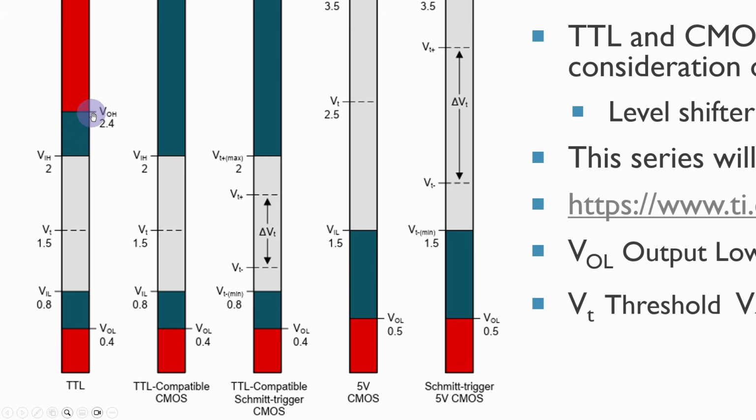Now this is actually underneath the guaranteed minimum output voltage of 2.4 volts, but it was a little bit above the voltage in the data sheets that says that it should count high as anything over 2 volts. And we also found that when we looked at a Schmitt trigger, there were 2 threshold voltages, so that if we had a fluctuating signal then we wouldn't end up with the output switching at random.